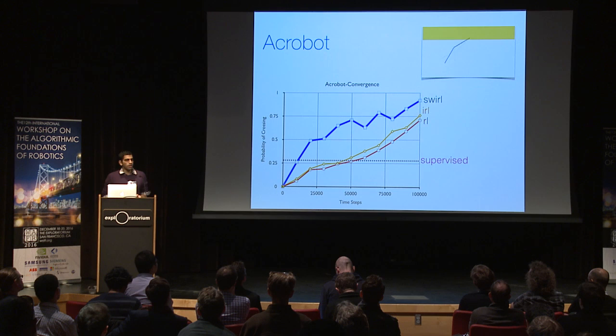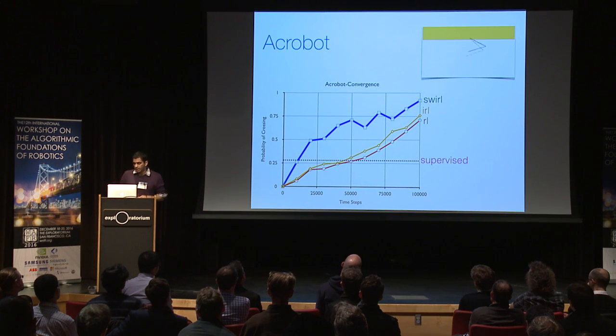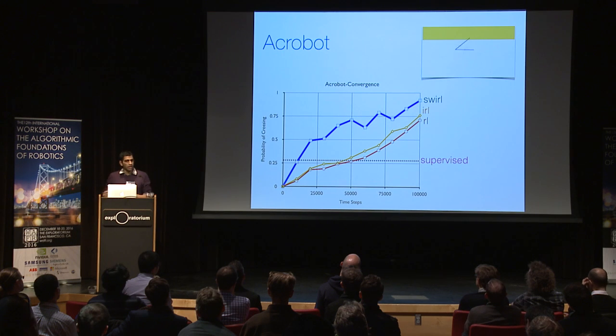Now suppose we were to take that RL algorithm and do some sort of inverse reinforcement learning, to learn a slightly better shaped quadratic function to go up there. You get a slight improvement, but not too much more. Then if we break this up into a whole bunch of subtasks with shorter horizons with these quadratic rewards, we get SWRL, which does a lot better than that. And this is intuitively what a control theorist would do, instead of just putting end-to-end RL on this: you would locally linearize and solve local objective functions. So this is intuitively encoding that.